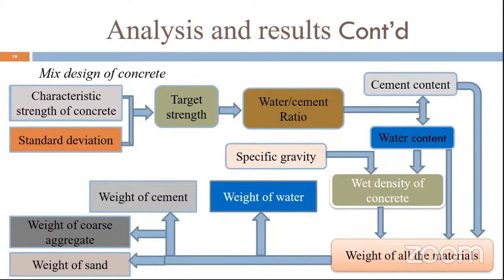On this stage, we determined the total aggregate required by subtracting the cement and water content from the wet density, to obtain the amount of all wet materials required.